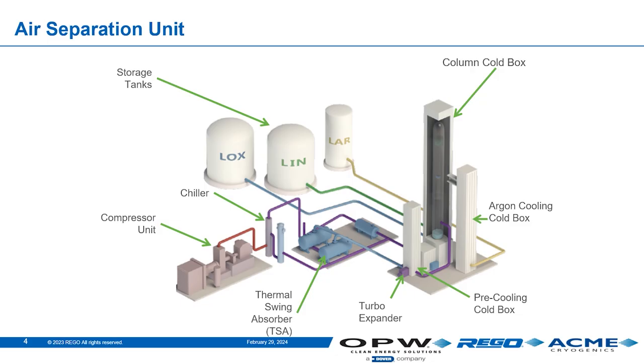You're zapping it with pressure and electricity, and as the gas comes in here, the temperature cools it, cools it, cools it. And if you guys remember, oxygen was the first one, based on temperature, to go from a gas. So the first thing that's going to happen is liquid oxygen is going to be made first, and then it's separated and sent to the oxygen trailer or a storage unit.